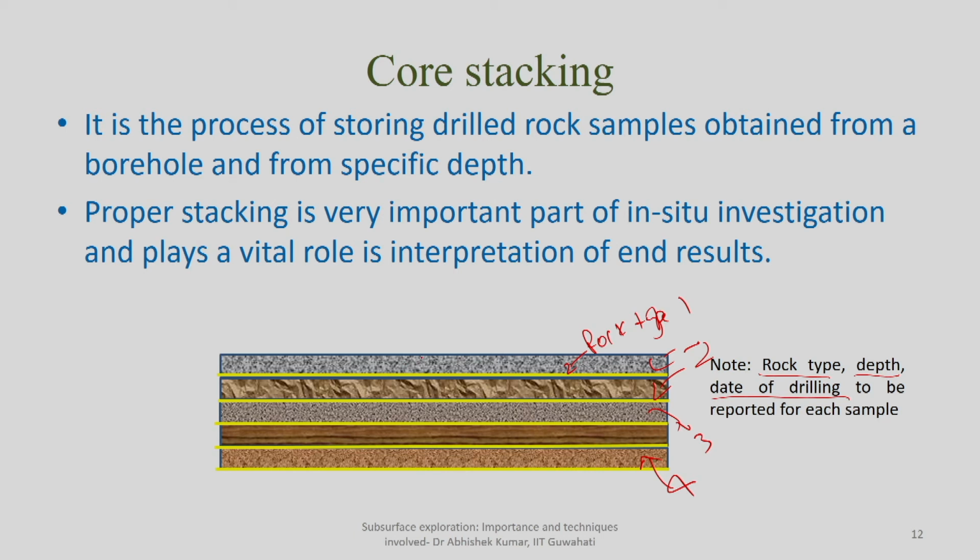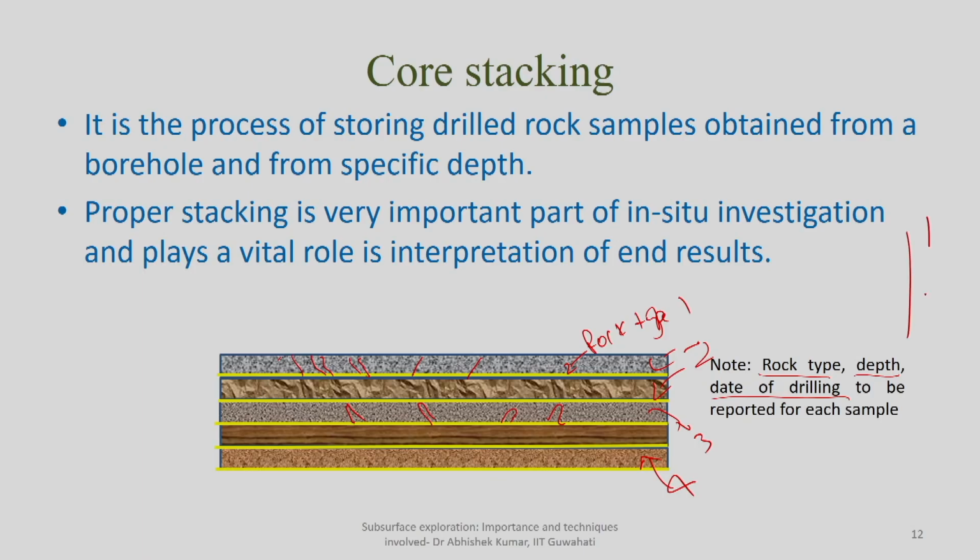It may be possible that you are having more, and then I have shown here very intact rock. There may be possibility there will be some kind of cracks here, which will not get you the entire core sample at one instant, but there will be some broken material in between, because of its natural condition, or because of the drilling operation, some crack had developed on the core. So proper stacking is very important, because finally you will collect those samples and you will get to know what kind of rock is available at different depths. So this rock information along with the soil information will give you an overall idea of this, my site of interest.